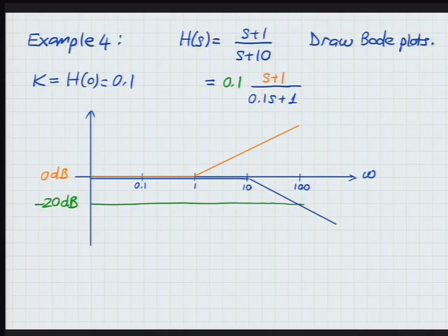And let's use red for this. So now we're actually plotting 20 log10 of |H(jω)|. So how do I add them up? Easy. Up until 1, nothing is really happening. So I'm adding 0, 0, and negative 20, right? So the sum stays at negative 20.